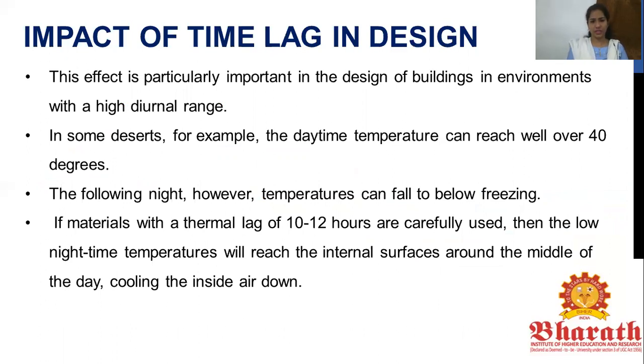So this effect is particularly important in the design of buildings in environments with high diurnal range. In some deserts, for example, the daytime temperature can reach well over 40 degrees Celsius, whereas at night it goes below freezing point. So if a material with a time lag of 10 to 12 hours is carefully used, then the low nighttime temperature will reach the internal surface around the middle of the day, thereby cooling the inside air down.